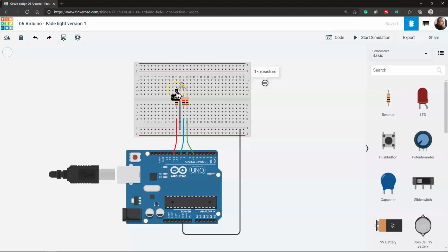So you can go here and see, well, that line is for red, this line is for blue, and this line is for green, and then this one here is a cathode. So they have a common cathode being the negative, and then the rest of them are hooked up. And again, through the voltage going through, they all come here and they all come out of here to complete the actual cycle. But depending upon how much actual voltage you apply to one pin, you get a certain brightness of that color.